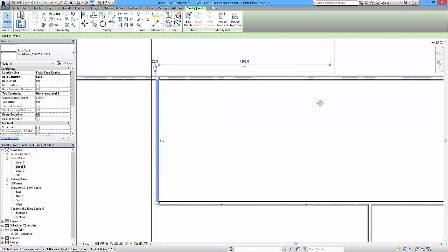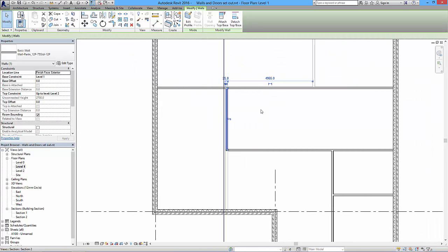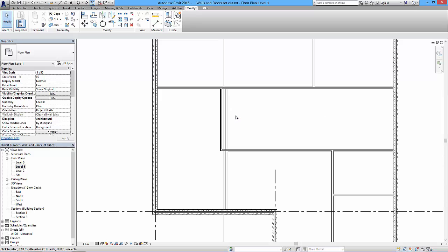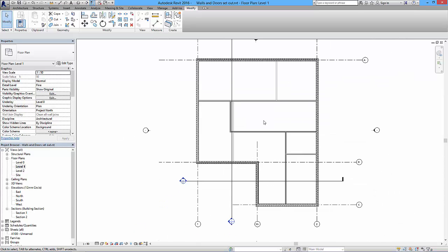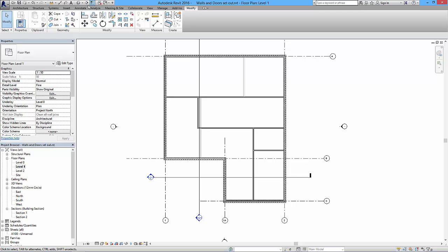Now we can have a look at the witness lines. Maybe you want this wall to be a certain distance from this face, not that one. So again, we can adjust these to position it there. So it's maybe 10 meters from that wall. So this is how we adjust all these things, given the tools that Revit gives us. So now, again, look at our 3D view.